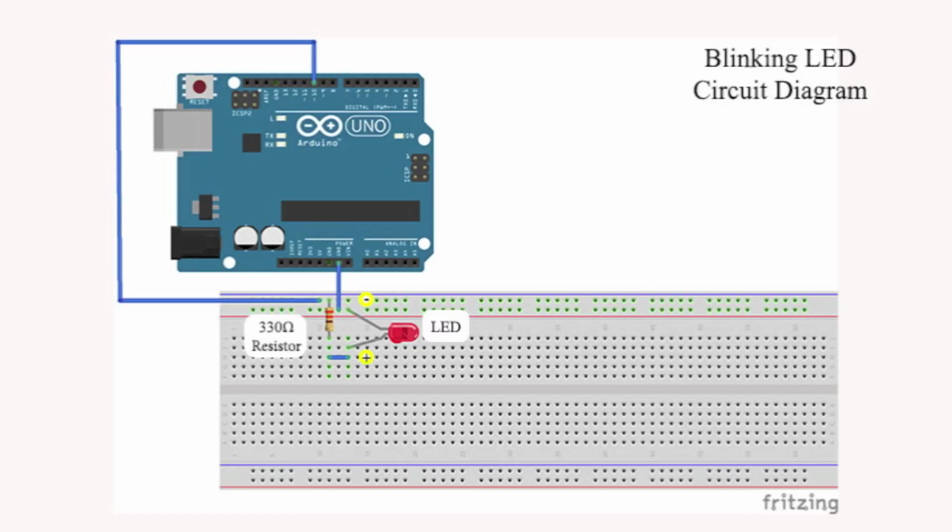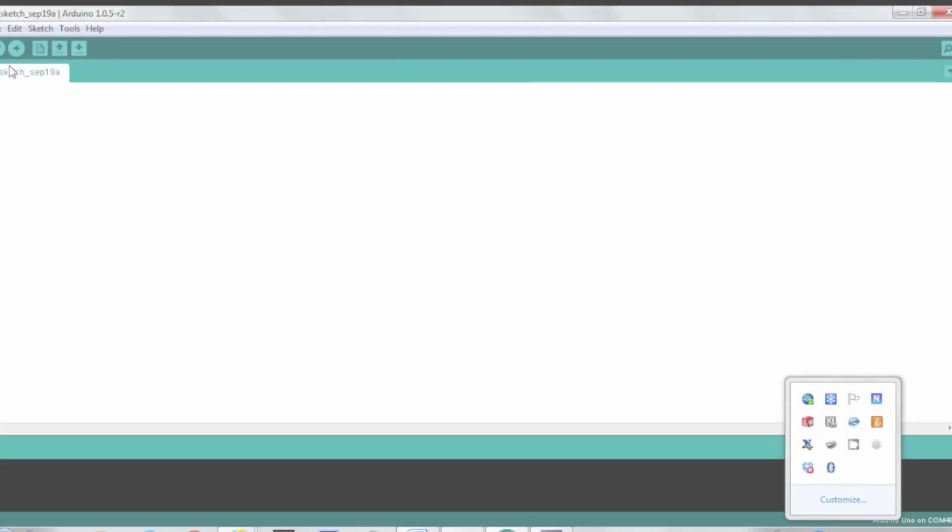Let's take us through a simple blinking LED sample setup procedure to familiarize with some of the codes. Before coding, we set up an external circuit as shown. A resistor of certain value is required to limit the current to the LED when 5 volts is applied. A typical LED can take a maximum of about 20 mA. We will not want to exceed that. For our case, we use a 330 ohms resistor and digital pin 10 for our voltage source.